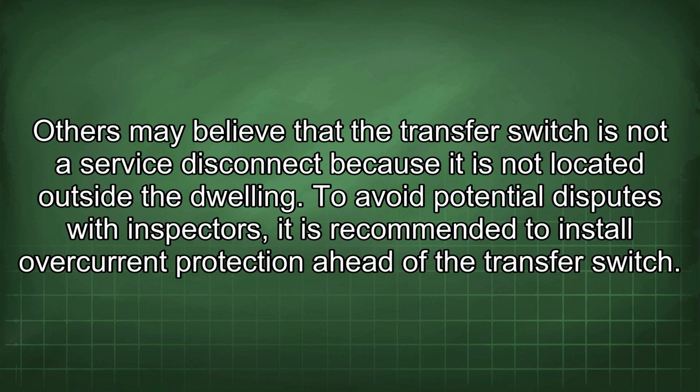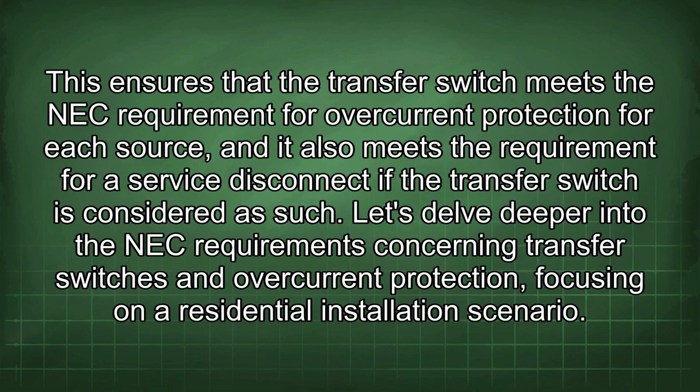To avoid potential disputes with inspectors, it is recommended to install overcurrent protection ahead of the transfer switch. This ensures that the transfer switch meets the NEC requirement for overcurrent protection for each source, and it also meets the requirement for a service disconnect if the transfer switch is considered as such.